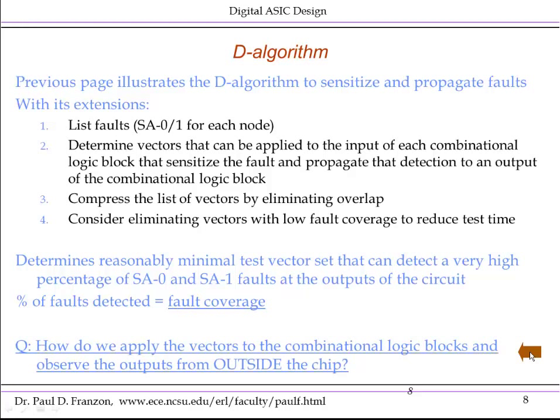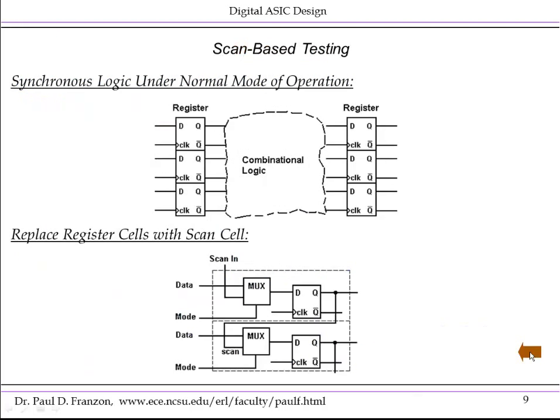We can't probe the wires in here, they're just too dense. We can't use E-beams to get the tests in or anything like that. We need some way to get the tests in and out. And the way this is done is scan-based testing.